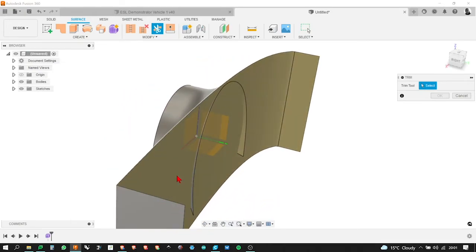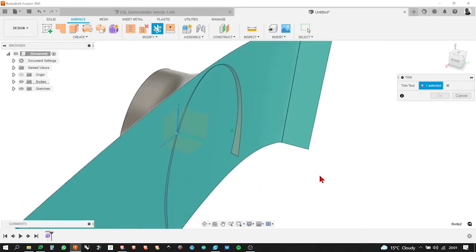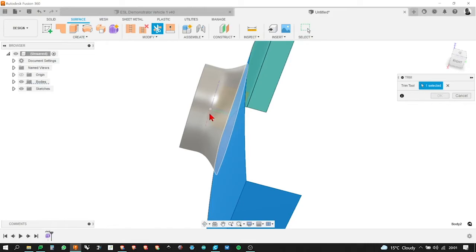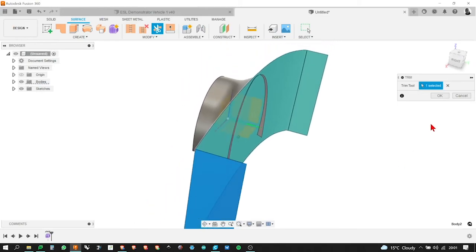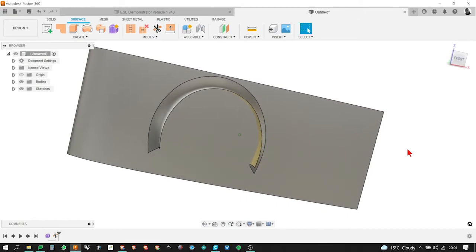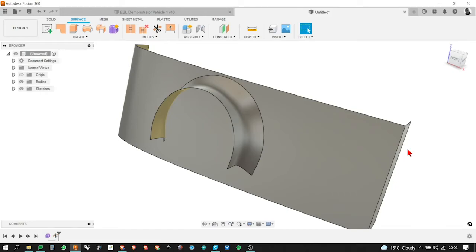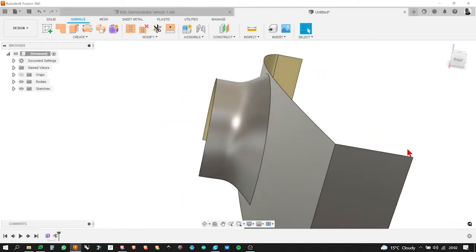And with the trim tool, we've got to think about what's cutting what. I'm trying to get rid of this little thin section that's sticking out into that surface, so I'm going to use this area as the trim tool itself. It's selected that as the trim tool, but it doesn't know whether I want to trim away this bit or this bit, so I need to click on the bit I want to remove. It should turn red, and it will trim it away. Obviously we'd have a hole in the middle of that, which I won't model now, but then you could trim away and get that full surface, stitch them together, and fillet it. But then you've got two surfaces which do absolutely match.